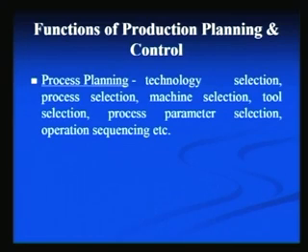But one thing which we should keep in mind while selecting the appropriate process parameters is that the parameters which we identify should be available on the machine tool which we select. For example, say the cutting speed is 500 rpm, but that speed is not available on the machine selected. So, that parameter cannot be implemented. That is why the process parameter selection should also take into account the type of machine which we have selected, the parameter range available on that machine, and the cutting tool which we have selected. For example, if the cutting tool is a high speed steel tool, for that tool we cannot go for very high cutting speed. So, all these factors are taken into account while selecting the appropriate process parameters.